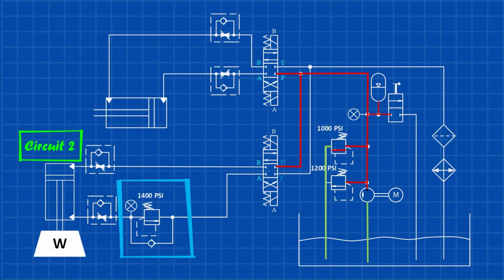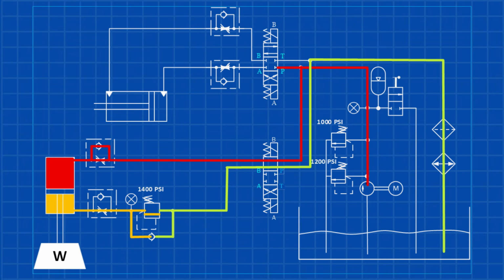It is commonly used to prevent an overhung load from running away or free-falling when the directional valve is shifted. A counterbalance valve provides controlled resistance to the overhung load and keeps the cylinder under control. A simple flow control valve is not always suitable for this application. Restricting the flow leaving the cylinder can create excessive pressure on the rod side, potentially causing cylinder damage or failure. The counterbalance valve is designed to control the load safely while preventing this excessive pressure buildup.